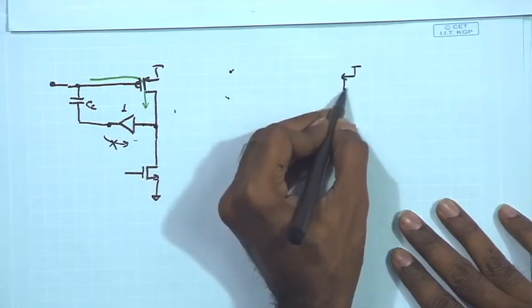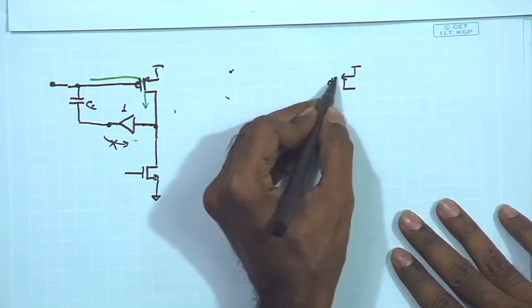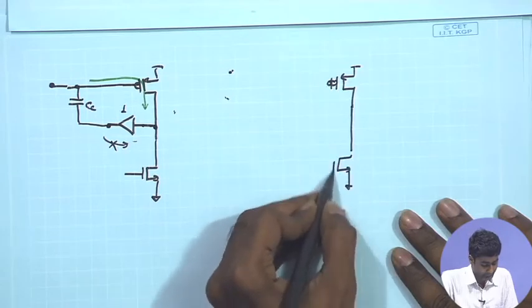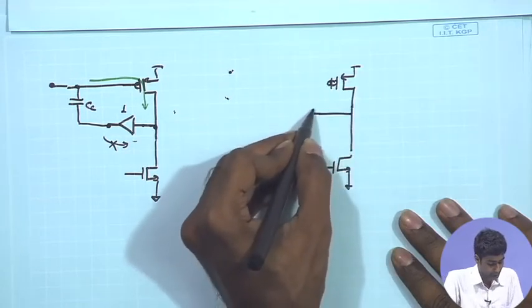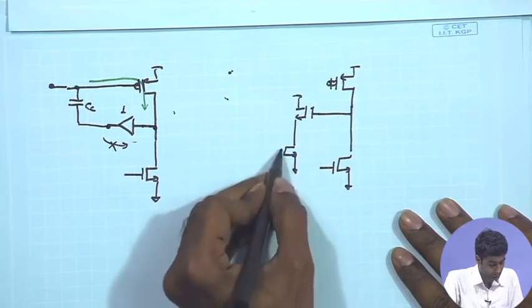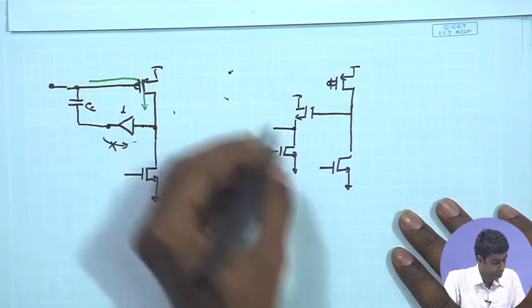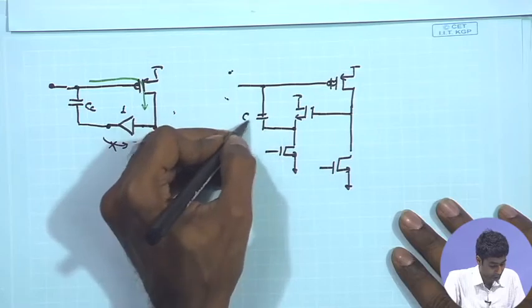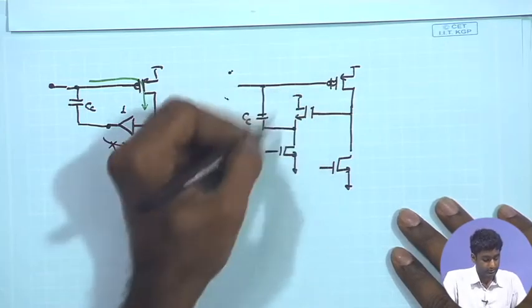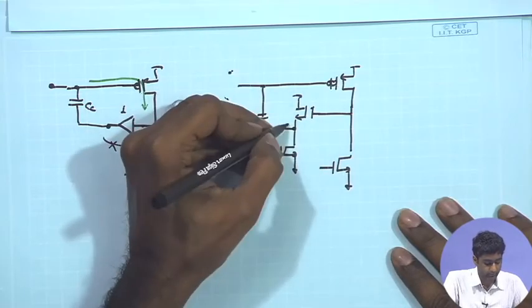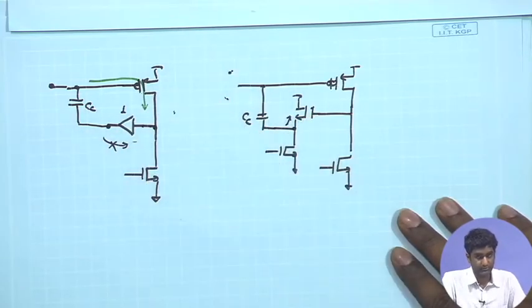So, in that case our circuit will look like this. You can have another bias point over here, and this particular point goes to CC. So, this is one particular scheme where the overall output impedance of this stage is given by 1 upon GM of this transistor, which can be made to be relatively low.